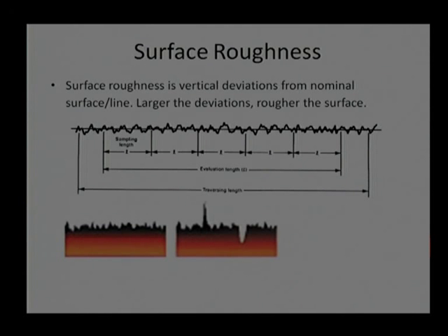Now, from a tribological point of view, as I mentioned earlier, we will prefer a low surface roughness value surface compared to a high surface roughness. In other words, I will prefer the left-hand side image compared to the right-hand side image. Maybe the average surface roughness of these two comes to the same, because there is a valley over here and a peak over here. If I sum up these two, I may get the same results, but I will prefer this portion compared to this portion because of the lesser value of the peak, but this is again at the start only.